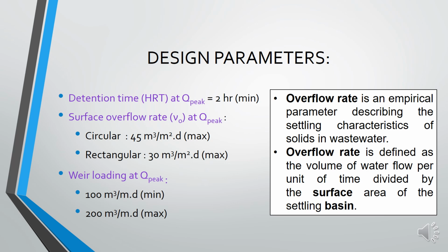Now these are the main design parameters of the primary sedimentation tank. Let's have a look. Here, the detention time, or the hydraulic retention time at Q peak, must be around 2 hours. 2 hours as a minimum.